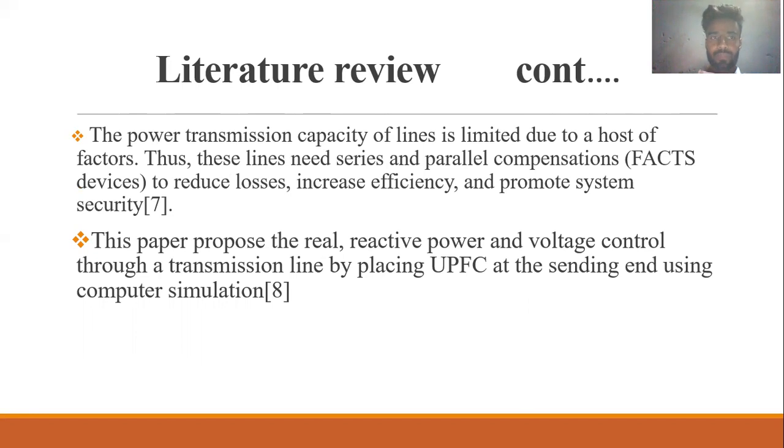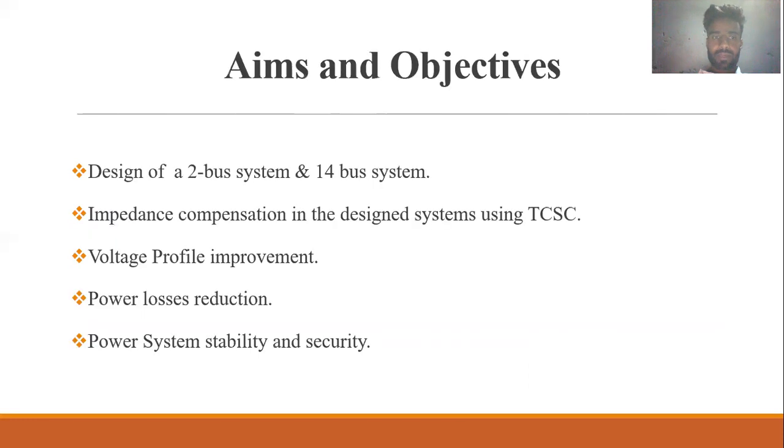We actually studied a comparative analysis of FACTS devices. For the next paper, we studied real and reactive powers and the voltage profile, and how much they are going to improve for the power transmission lines. By placing UPFC and TCSC, we did a comparison between them, and we got the solution that TCSC is better and simpler than UPFC.